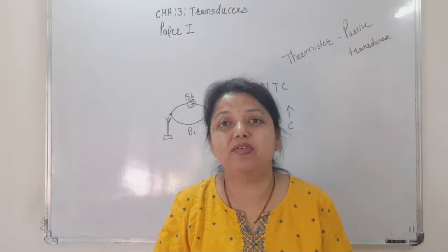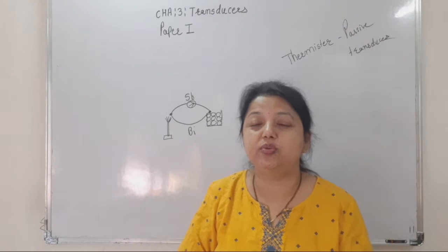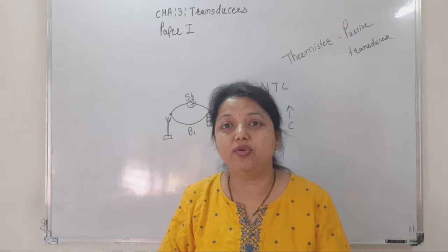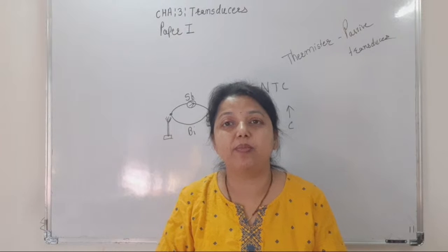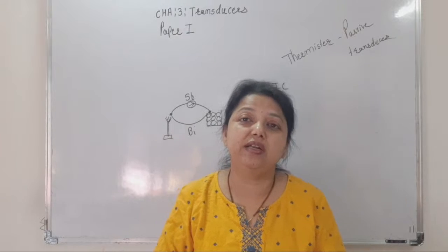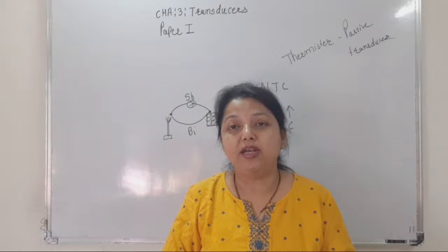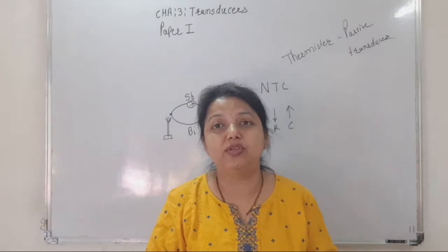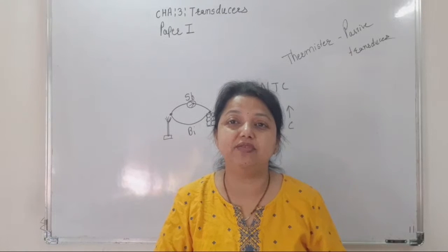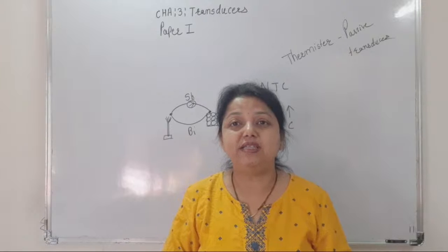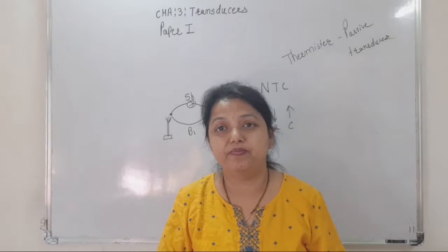And see that graph in our last lecture, we just discussed that graph, that along x-axis we plot different temperature. We start from -100, 0, then 100, 200, 300. The sensitivity of this thermistor, it works properly from -100 to 300 degrees Celsius. Means variation in temperature is properly monitored from -100 to 300 degrees Celsius, and the change in resistance is maximum. This is the high sensitive resistance. Means for a 1 degree Celsius change, there may be variation in the resistance by 6 ohm.